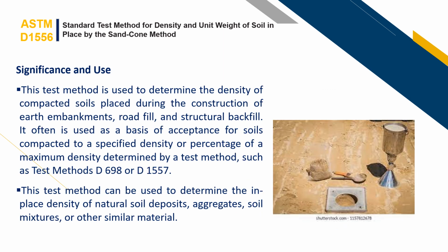Now for the significance and use of the standard test method. With respect to the results of this test, this test method is used to determine the density of the compacted soils placed during the construction of earth embankments, road fill, and structural backfill.